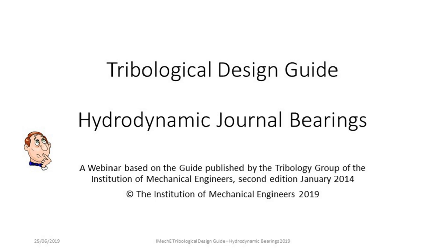Moving on. The other question we've got here is, can we use water as the lubricant for the journal bearing? Sure. Water can be used. Why not? The viscosity of water is very much less temperature dependent than the viscosity of hydrocarbons. But it is very much less viscous than the majority of the commonly used hydrocarbons. But sure, you can use water.